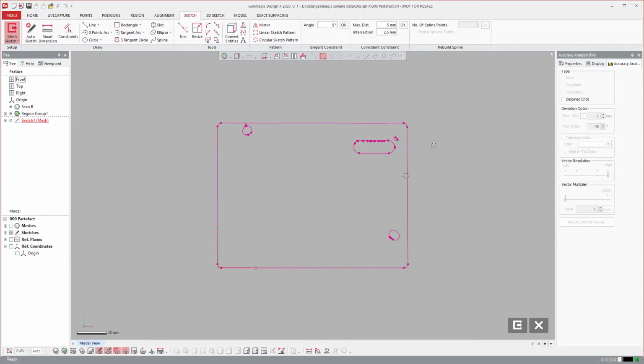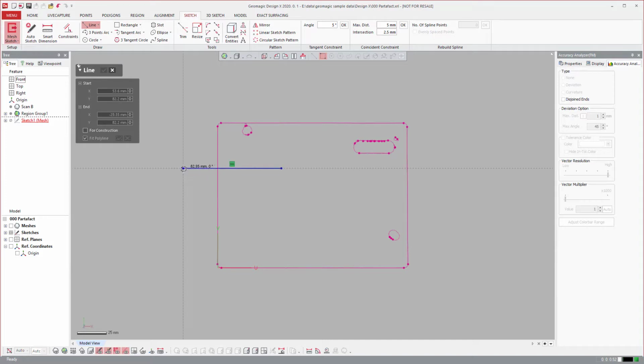But the main idea is DesignX gives you the ability to come in and draw things wherever you want to, just like a regular CAD, or you can best fit. So if I select those areas, that turquoise area is what I've selected, and it will best fit the sketch geometry to the data in the scan.